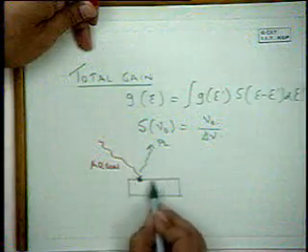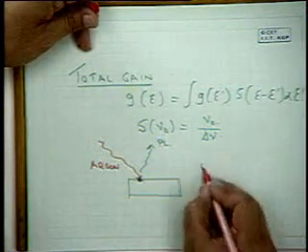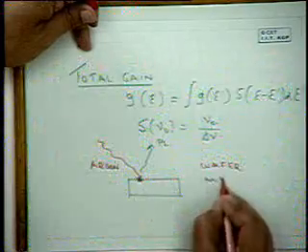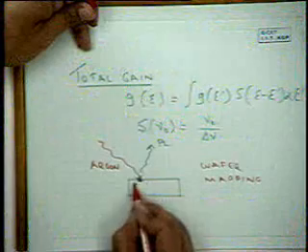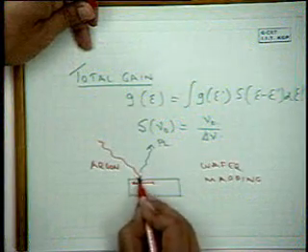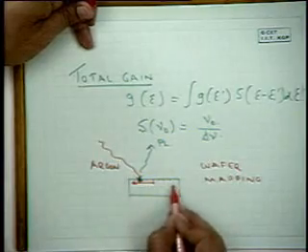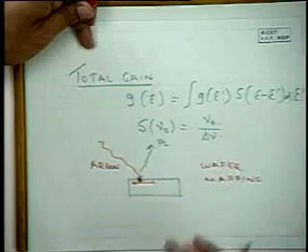This is called wafer mapping. We should obtain photoluminescence from different spots on the wafer to see how uniform it is. The spatial variation of nu 0 and delta nu has to be examined.